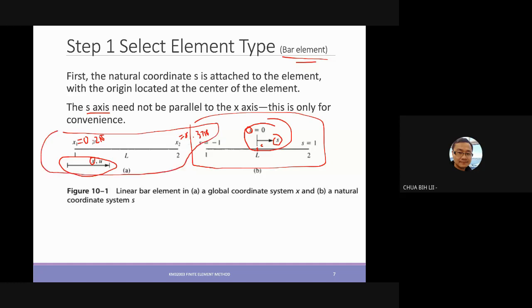But for the computer to get all these exact coordinates from every single element would not be efficient or optimized. Therefore the isoparametric or natural coordinate system comes in to define a simpler form of coordinate. Just define the center as 0, then whatever is to the left is -1, to the right is 1. It's very straightforward, so it would be more efficient.